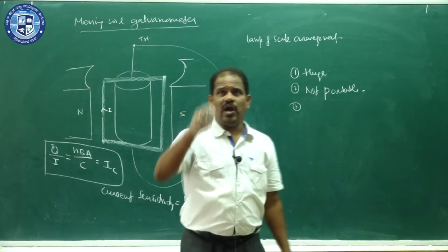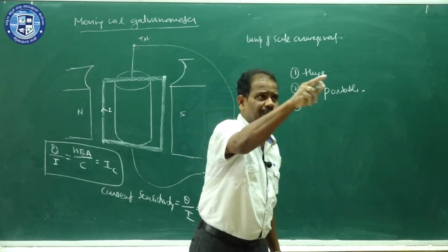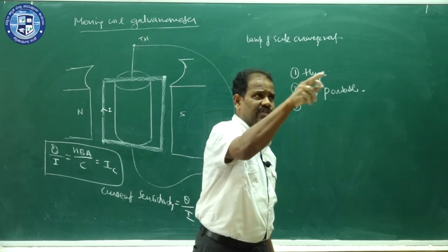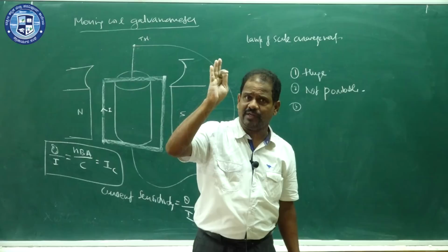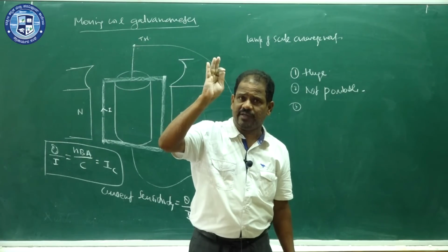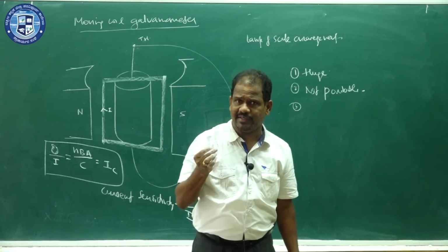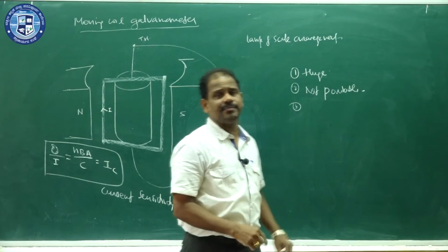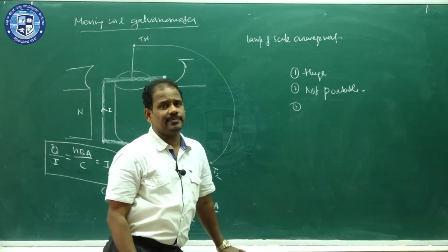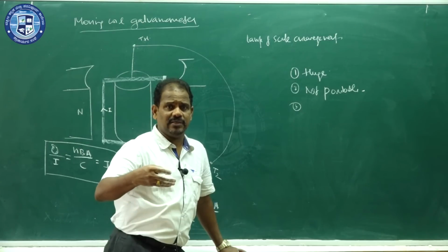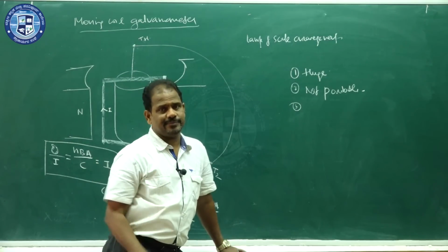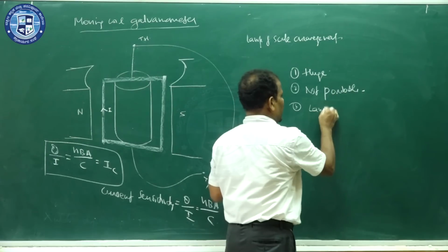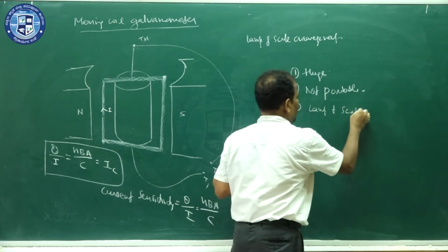First you see how much the light has moved on the scale. Finding the distance the light moved on the scale, you see how much the mirror turned. How much the mirror turned will give how much the wire turned. How much the wire turned will give how much the coil turned. So it is an indirect method. The more indirect, the more the error. Since it is seen through the lamp and scale arrangement, the error possibility is more.